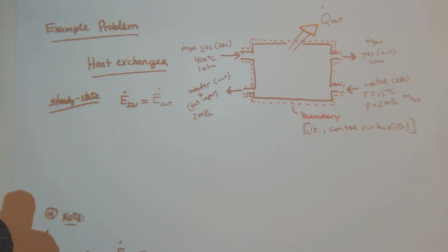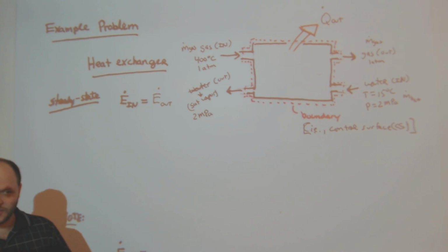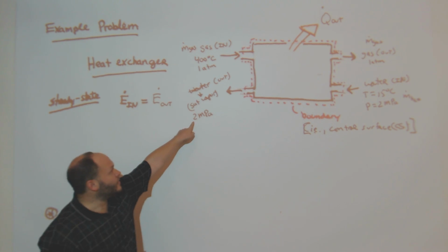So if you want to remember this, the quick way is to think about, well, someone mentioned that on Mythbusters, they put somebody in an evacuated room and had a water bottle. They started decreasing the pressure and the water bottle started to boil. One way to think about it, you go to the top of Mount Everest, the water gets sucked out of you because you decrease the saturation temperature, right? It's lower pressure, so the water is like boiling out of you almost. It really evaporates easier. Or with a pressure cooker, you pressurize it so you can cook at a temperature above the boiling point. So increase pressure.